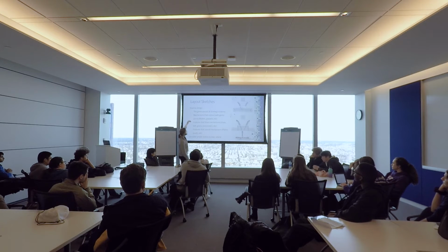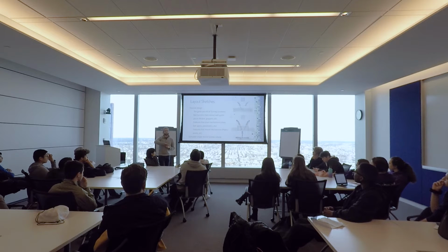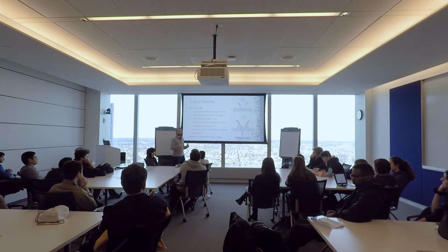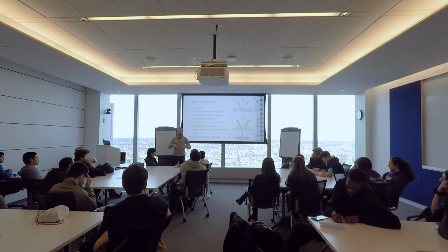you then model the features that drive the mechanisms, so the chains, the gears, the pulleys, whatever it is. And then you model the features that mount the mechanisms, that hold all that stuff in place, so the plates, the pivots and the bolts and that kind of stuff. So you basically work almost completely backwards from what it seems like it would be. You start at your end goal, you work on where the end effectors physically need to be, sans all the other hardware and driving components. Then you figure out how they're going to be driven. Then you figure out how all that stuff is going to be held in place physically. And then you figure out how it's going to be mounted to the robot, in that very specific order.